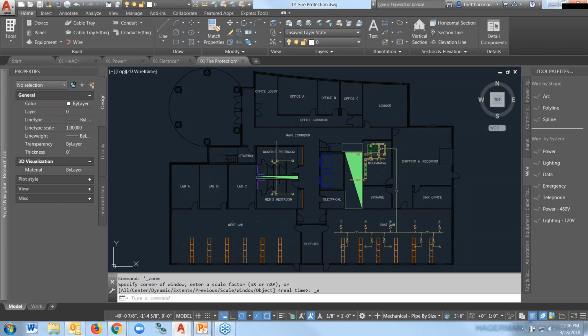If I already have a floor plan created in standard AutoCAD, can I load the MEP toolpath into the standard CAD to access it, or do I have to open the file in MEP altogether? You can use a drawing that you received from your architect, maybe a 2D drawing of the floor plan. You can place it in there. It's just that when you go to a 3D view, you will only see it as 2D. But you can draw your MEP on top of that at the correct elevations so it looks correct in plan view, and you get the correct data for length of duct and length of wires by using the 3D features in here.